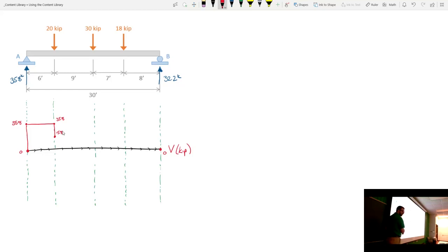Nothing. So, I go over, go over, go over, go over. Whoa! I'm at 15.8. The beam is telling me to drop down 30. If I'm at 15.8 and I go down 30, what's that put me at? Negative 14.2.